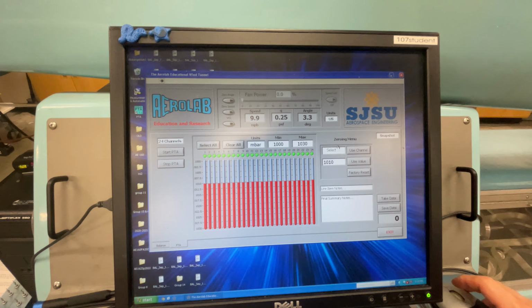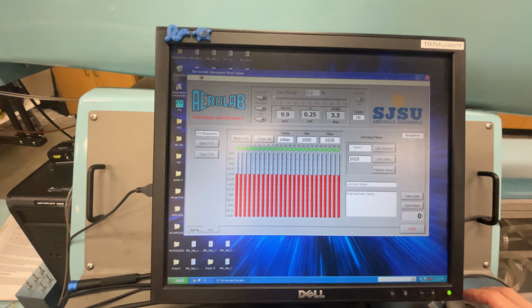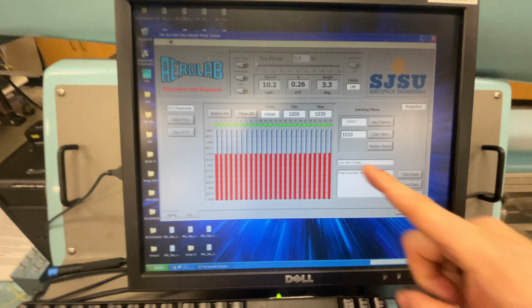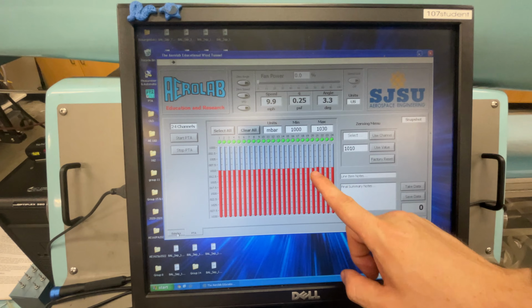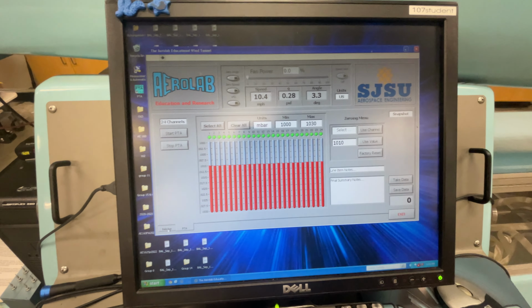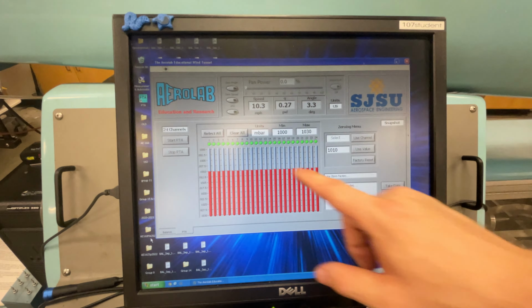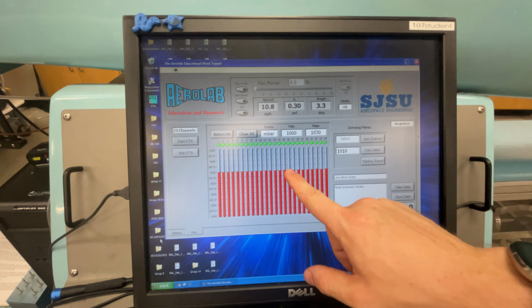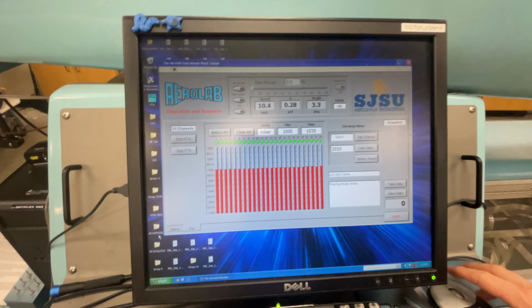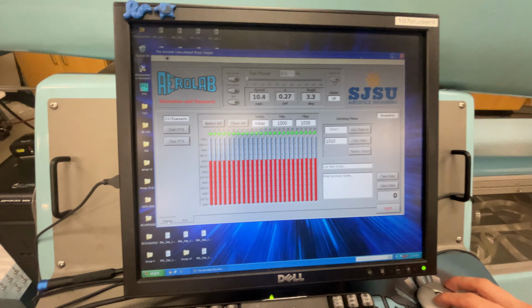The rest of the software functions pretty much identically, with one other small caveat. When taking pressure data, it takes a lot longer than force data. Even at its fastest, it'll only take about 10 pressure measurements per second, whereas it'll take about 100 force measurements if you let it. We'll get to that in a moment.